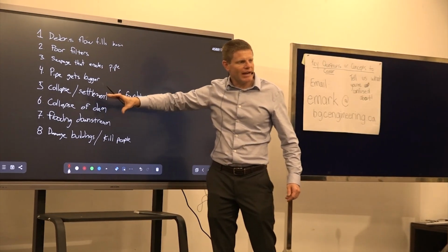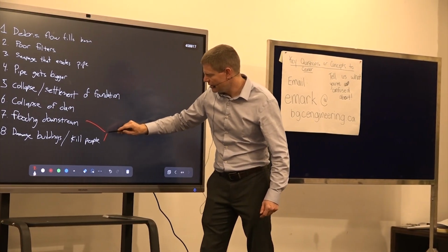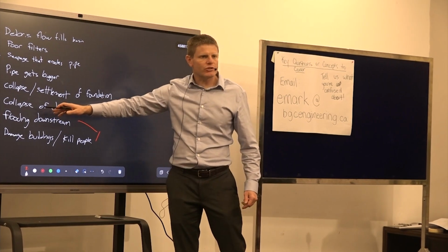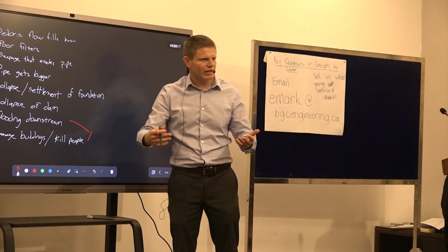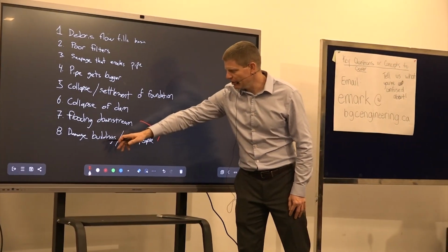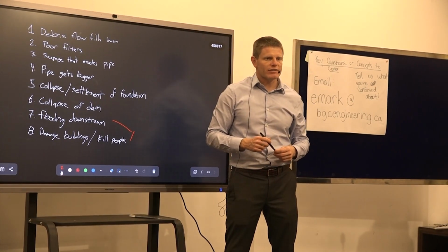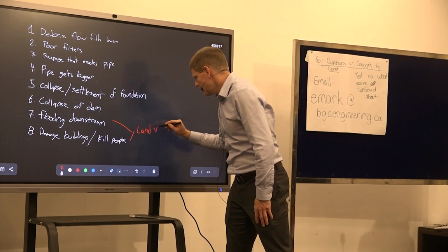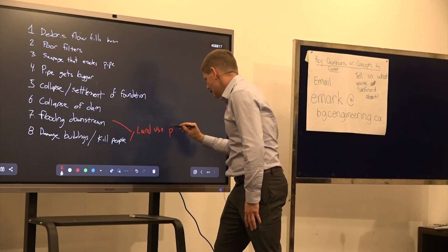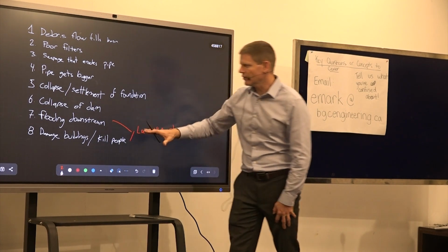So I'll start. This happens, and we manage the risk by managing these items here. You could prevent the flooding downstream by looking at the size of the channel and having a channel downstream that prevents the flooding, or you could protect the buildings so that the people aren't killed. Or you could use land use planning, I guess is what you said. So you could have land use planning downstream that protects people from this failure mode.